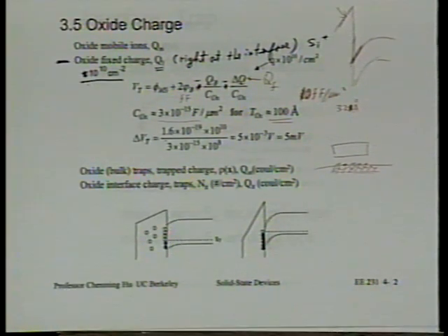But indeed, we do expect some incremental increase, and that's one reason I agree with the statement earlier. They will be closer, so there may be even more interactions, maybe more scattering. But we're not going to be able to increase the vertical field that much. That's one of the difficulties of scaling we will see. Okay. We're already using 20 angstrom of oxide. How much thinner can we make it?